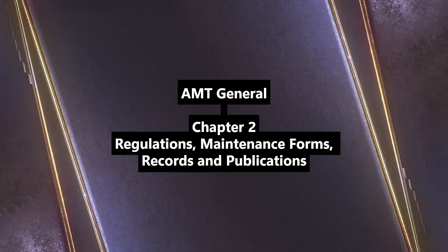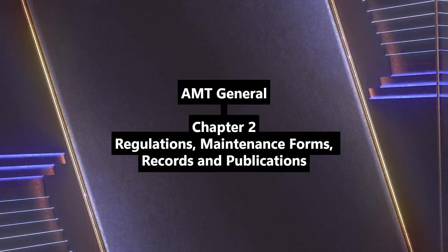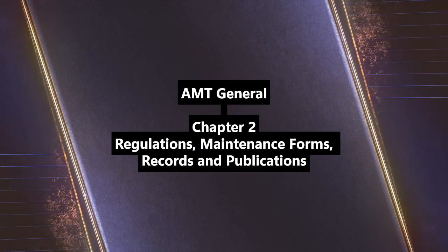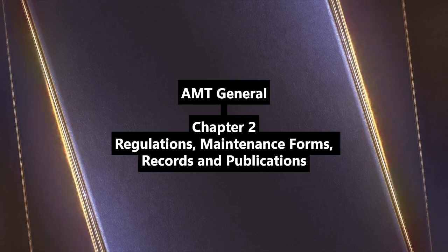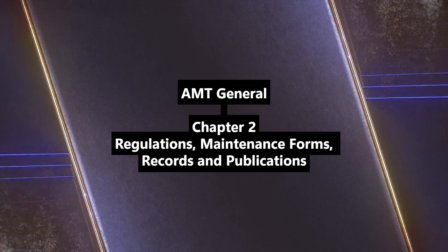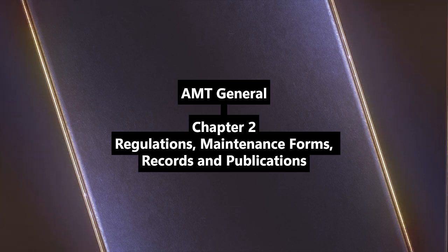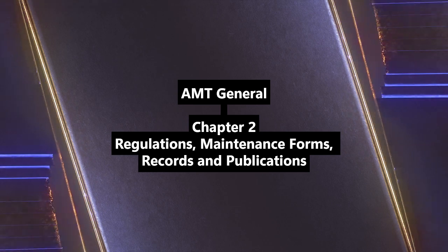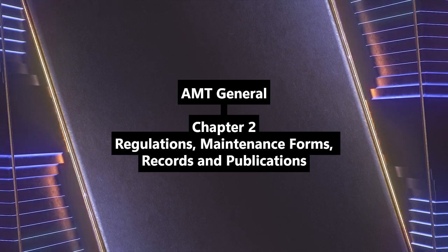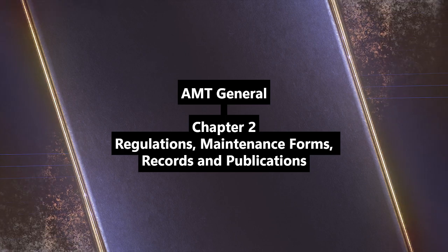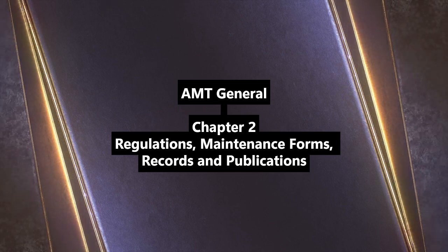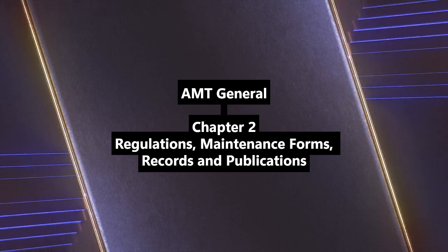Section 43.16, airworthiness limitations. Back to mandatory stuff. Yes. Technicians must have and comply with the airworthiness limitations section found in the manufacturer's manual or ICA, required by Part 21.50, or in ops specs, Parts 121.1135, or approved inspection programs, Part 91.409. These are mandatory replacement times or inspections, non-negotiable.